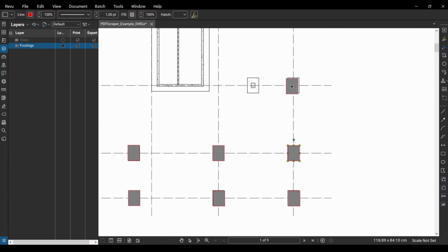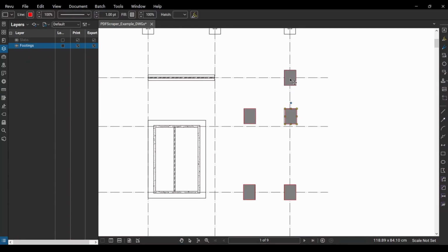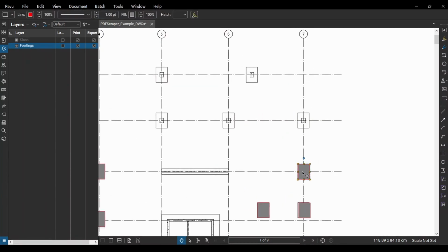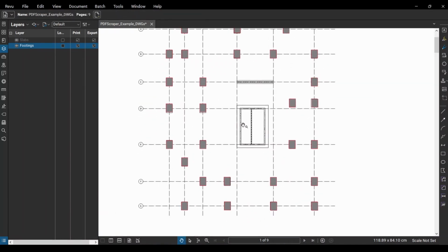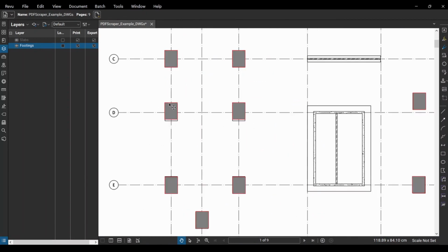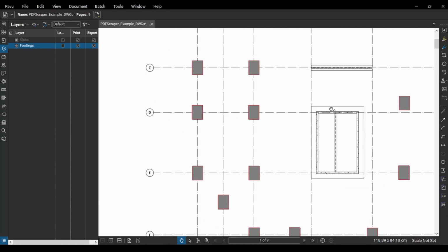So you'll actually calculate all the loads coming down these columns, and then as soon as you know the capacity of the soil you're working with, you can actually get it to automatically size these pad footings for you and optimize the size of them. So I'll just keep copying that around. And there we are, done. So I've got a footing for each of the column locations that are in there. I might just nudge these ones just down a little bit.